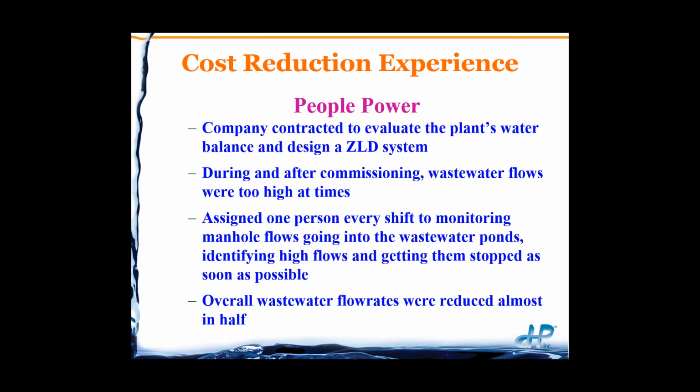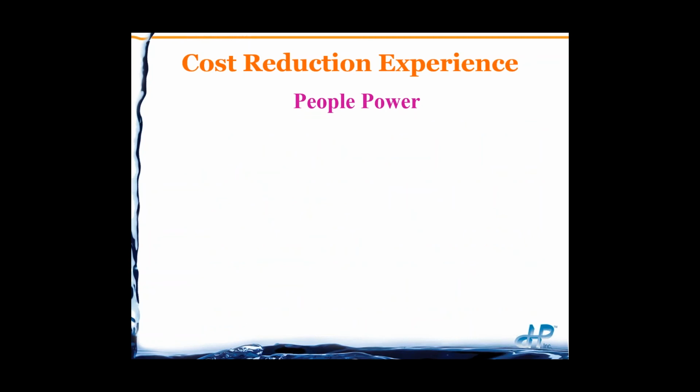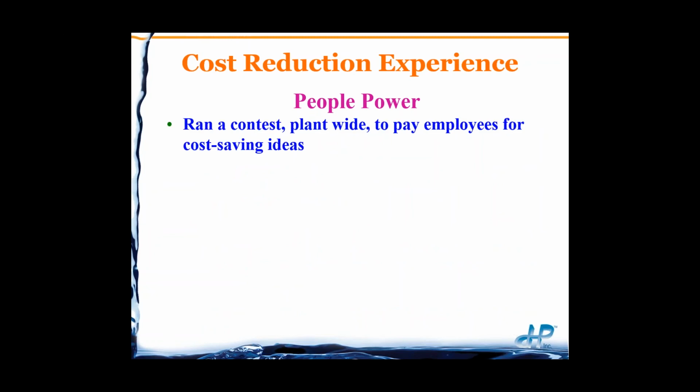As far as cost reduction, the lesson here is, had we done this before we designed this zero liquid discharge plant, we could have controlled the wastewater flows to the point that we only had maybe half of the flow, and the actual ZLD system would have been much smaller, saving millions of dollars. So I want to stress from the get-go that people are going to be your biggest resource.